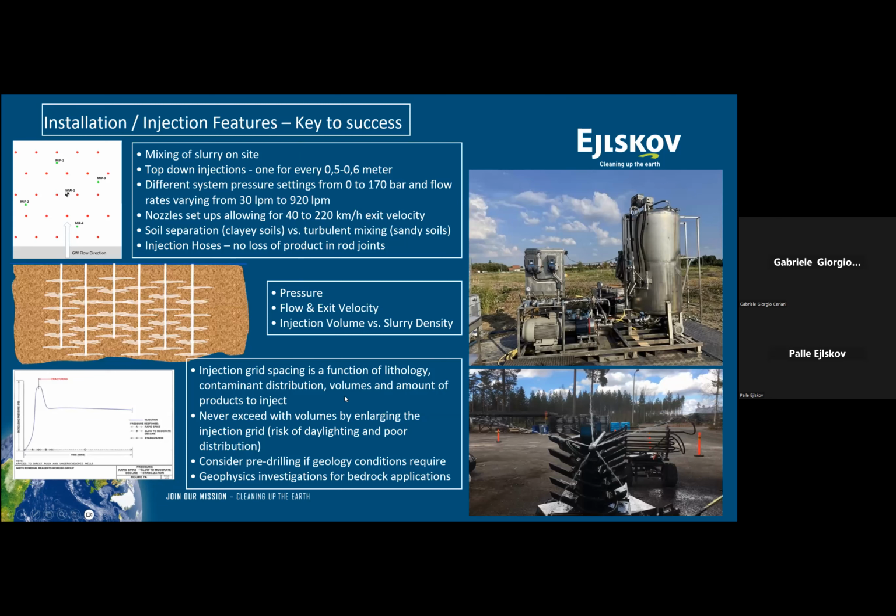And ultimately, then it goes down to the technicalities behind the applications. So when we look at the key to success, as Mike was explaining, it's a tight fit between the design and what we deliver on site. So when we look at the basis of the application, we normally work on triangular grid spacing that can go from 1 meter to, let's say, 2.5 meters, depending on the type of geology, the depth of the contamination, the amount of contamination that may be present. So if we have hotspots carrying a lot of contamination tight in soil, we may have to do very surgical injections to apply the product correctly.